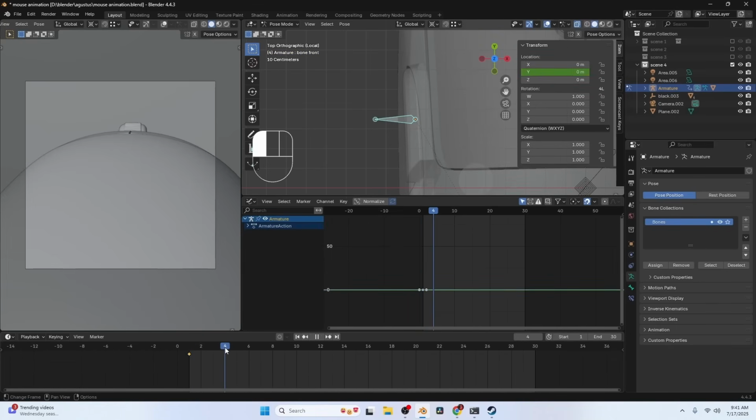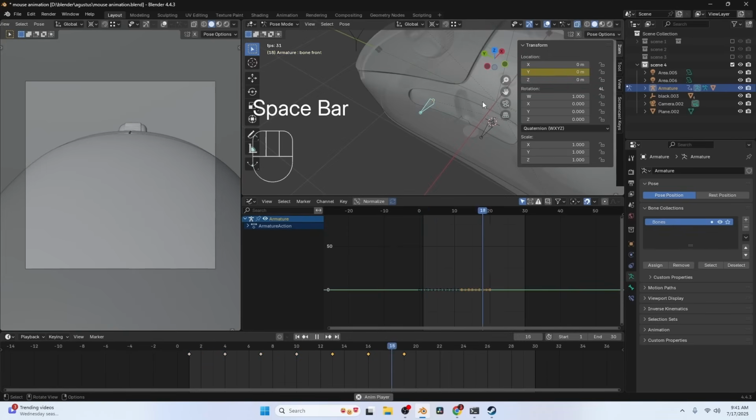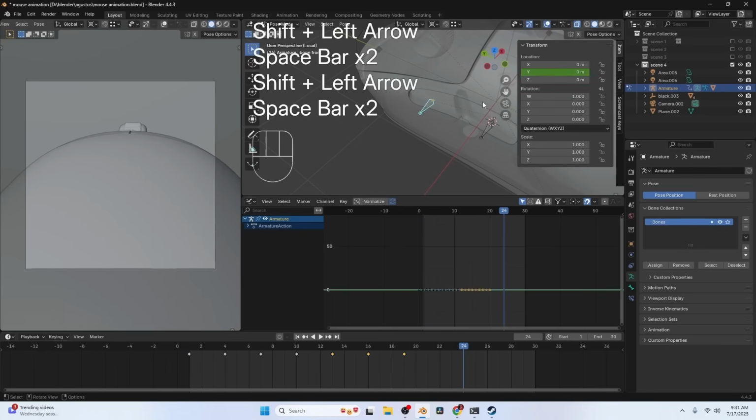I'm going to move at the fourth frame. Move it back here. Right click, insert single keyframe, then just duplicate this one, move it to the 7th frame. Then A to select everything here, Shift D, duplicate it, put it here, Shift D, duplicate again, put it here. Let's see the animation by hitting the spacebar. We have something like this. It's pretty good.